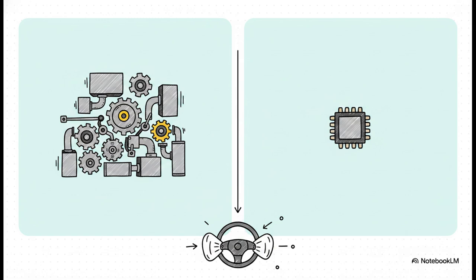To really appreciate why MEMS is such a massive game changer, just look at the automobile crash airbag deployment system. The old tech required several bulky accelerometers made of discrete components, and they had to be mounted in the front of a car with totally separate electronics near the airbag itself, and it cost over $50 per device. But MEMS technology allowed engineers to integrate the accelerometer and the electronics onto one single tiny silicon chip for just a few dollars. They're smaller, lighter, vastly more reliable, and a mere fraction of the cost.